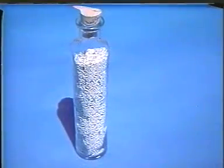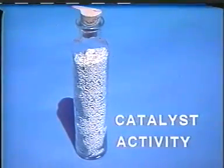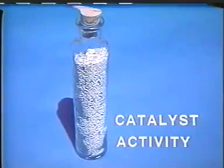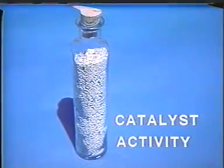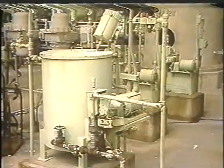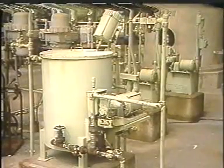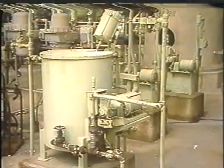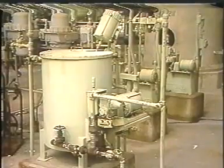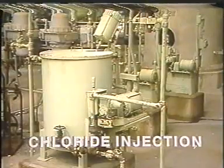To promote the desired reforming reactions, the catalyst must be active. There are several variables that affect the catalyst activity. You have already learned that coke deactivates the catalyst, reducing product yields and quality. Another variable that affects the catalyst activity is the chloride level on the catalyst. In order for the catalyst to remain active, a certain level of chlorides must be maintained on its surface. This level can be adjusted by injecting chlorides into the feed or the recycled gas streams.